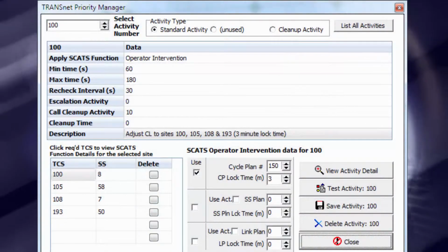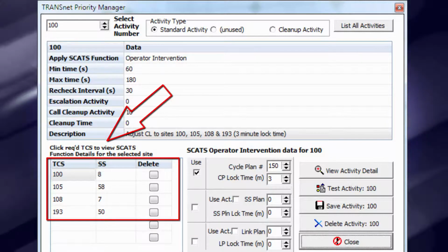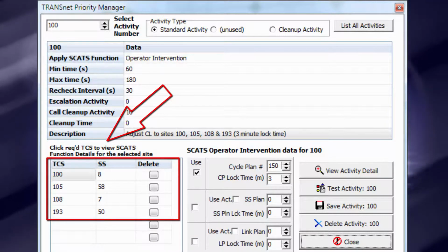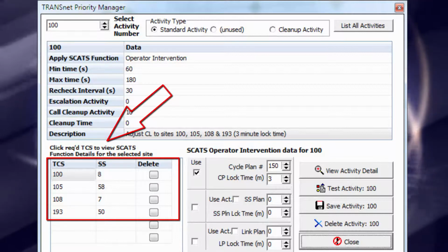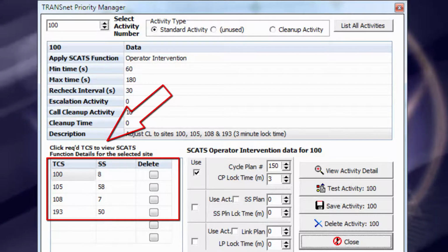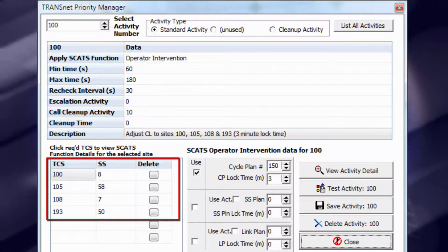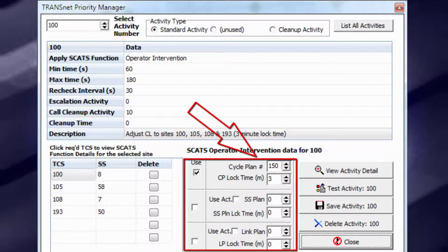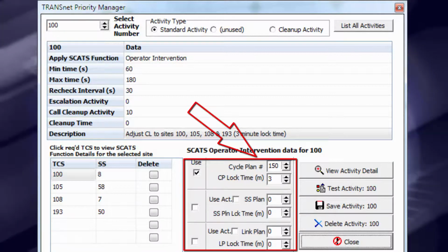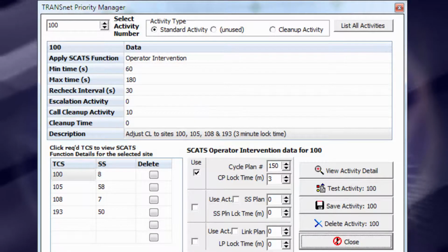When a trigger condition is detected, the system can be programmed to control one or more intersections. For example, if a bus is detected behind schedule, rather than waiting for the vehicle to be detected at other specific locations before commencing further priority improvements, corresponding cycle length or phase times might be increased at intersections further downstream to proactively provide additional priority to assist to restore the schedule.